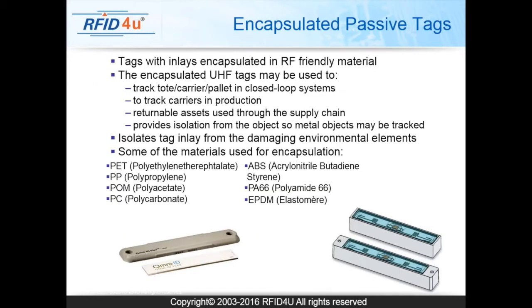So passive tags can be encapsulated into RF-friendly material. Not all plastics are RF-friendly. If you remember not too many years ago when you were recycling plastic bottles, you could recycle some plastic bottles, but you couldn't recycle other plastic bottles because they were made, in this case, oil-based versus water-based. So the same thing is true with all plastics. If you're going to be working with different plastics, you need to make sure that the plastics are RF-friendly.